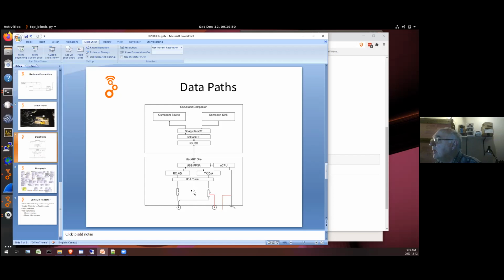And now here's the interesting thing. You might have to zoom in to see this. Inside the HackRF One, there are solid state switches. In receive, there's a switch that brings this little preamp in or out of the receive path. So that's what those two little switches do. And then there's another switch that controls whether the regular antenna port is connected to the receive path or the transmit path.